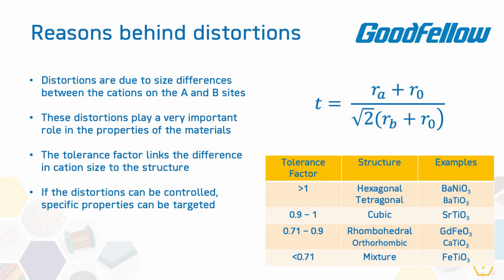Now, if we swap strontium out in a titanate for something that is smaller, such as calcium, mathematically we get a smaller tolerance factor, and this predicts a change in structure toward rhombic. And conversely, if we swap strontium out from the cubic with a tolerance factor of 1 to the bigger barium, again, the tolerance factor then mathematically goes above 1.